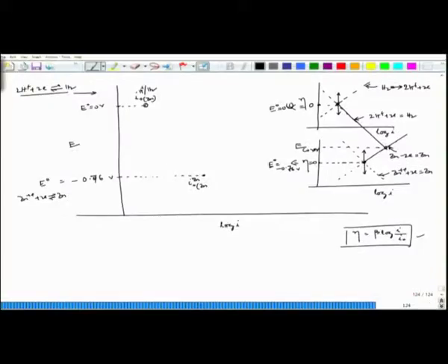This is the E corr point, and the corresponding current density is I corr, which is nothing but Ia equal to Ic. Whenever we have this situation, whatever electrons are generated are consumed, so there is no net accumulation of charges for this electrically isolated zinc piece in HCl medium.